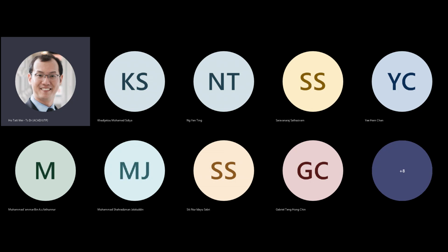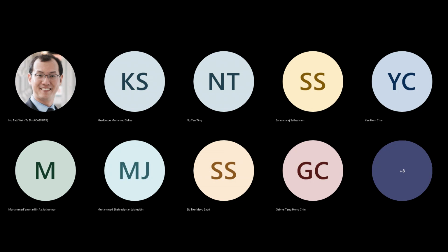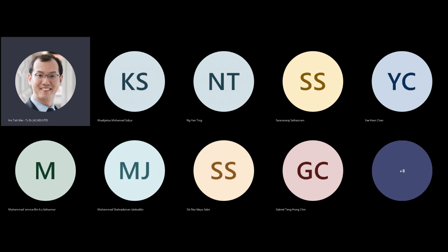You need to understand that these equations were experimentally derived, meaning that this factor of 1.2, 1.3, 1.1 is actually fitted from data, right? So it just gives us a sense of how the current varies with all the geometrical parameters, electrical parameters, and material parameters, mu here.